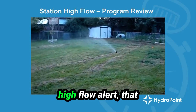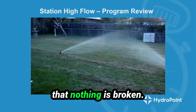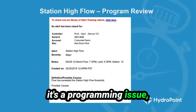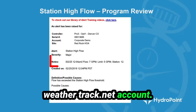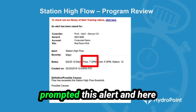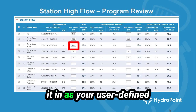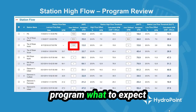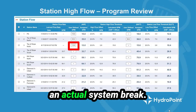So if you get a station high flow alert that fits this description, first go out and verify that nothing is broken. Once your system passes inspection and we know that it's a programming issue, take that alert notification to the program page of your WeatherTrack.net account. In your alert notification, you'll find the value of the measured flow that prompted this alert. And here in the station flow section, take that value and plug it in as your user-defined assigned station flow value. Doing this will tell the program what to expect during normal irrigation and avoid having this alert raise again without an actual system break.